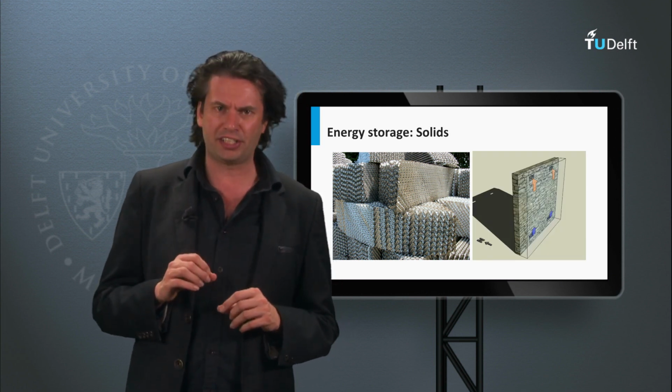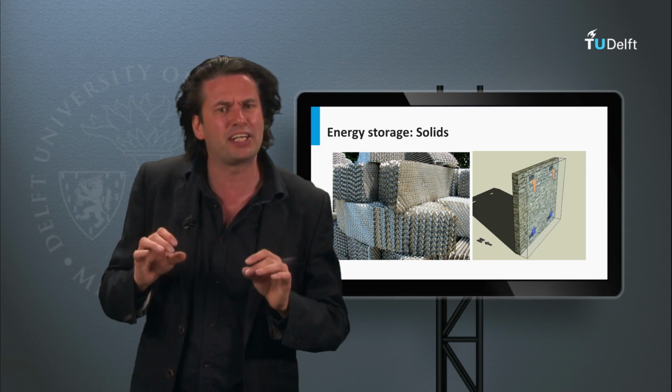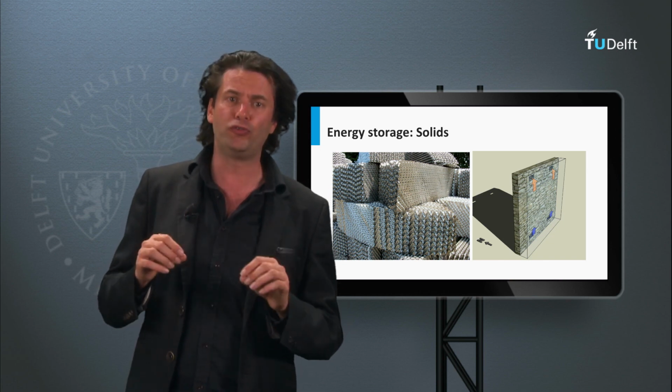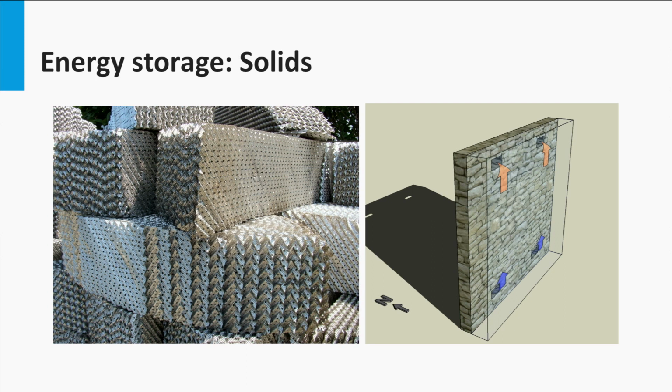Another way to store energy in solids is when thermal energy is provided in the walls and roofs of the buildings for storage. A case of particular interest is the collector storage wall, which is arranged so that the solar radiation is transmitted through a glazing and absorber in one side of the wall. The temperature of the wall then increases, and that energy is transferred from the wall to the room by radiation and convection. Some of these walls are vented to facilitate natural convection even more.